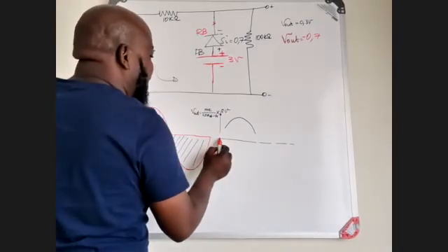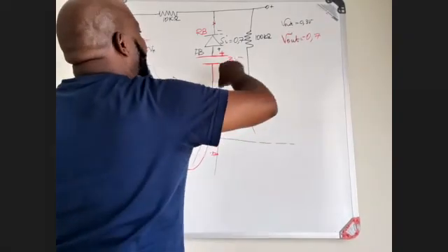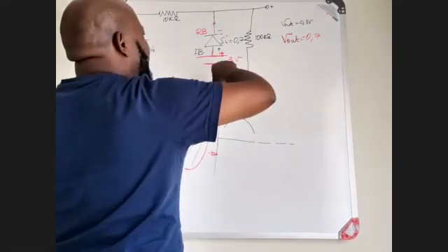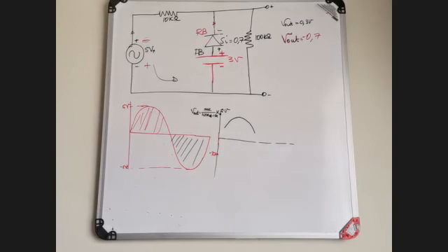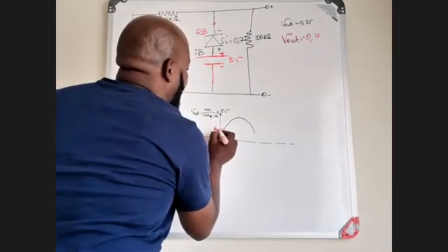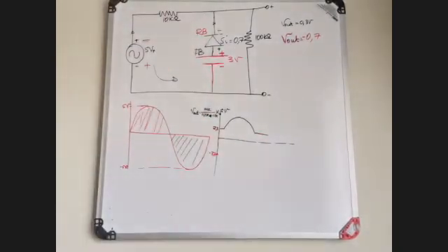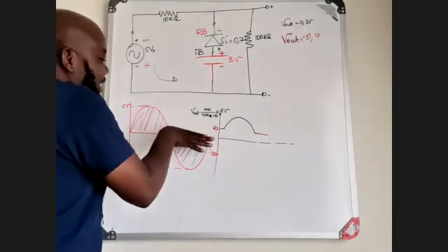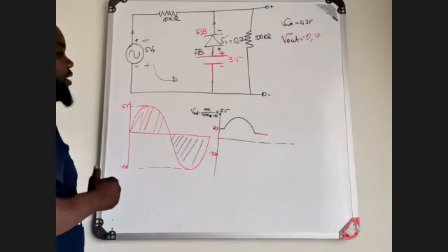Now, when you chop off the non-bias signal, if this is 3 volts, it's going to be 3 volts minus 0.7 volts, which is 2.3 volts, which means this is going to start at 2.3 volts. Then it oscillates all the way to your maximum, which means you no longer limit only the negative cycle, but you also limit even a portion of the positive cycle.